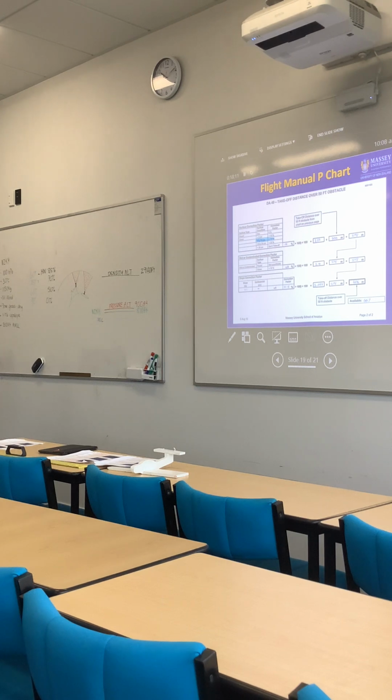This whole calculation is pointless if we don't now compare that figure to the distance available for takeoff. And so to find that, we go back to the operational data page for Ko-Fi Aerodrome, and we take a look at what the table said the takeoff distance was. And you see I've put that into the chart here, 667 metres. So to be safe, we need to at least be able to get airborne in less distance than is available. So we need 606, and the runway is 667. So there's not much of a margin there, is there?